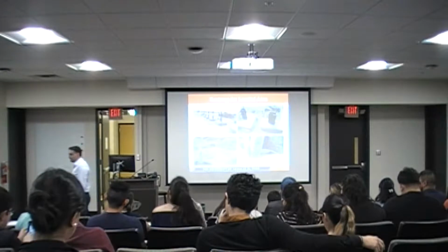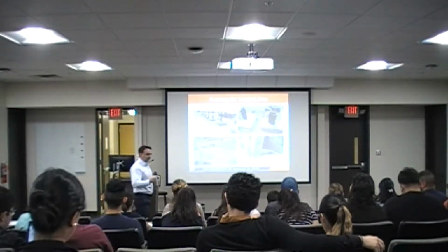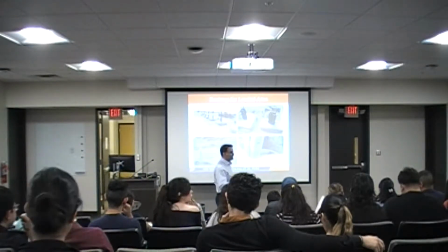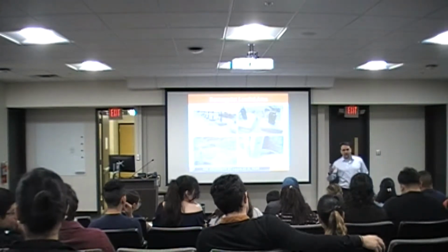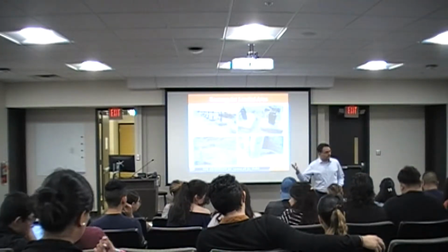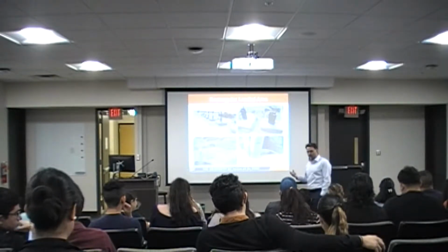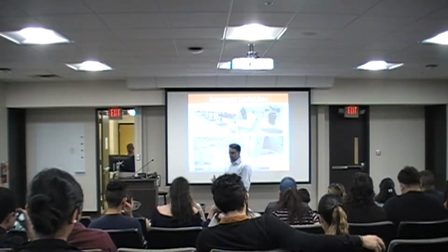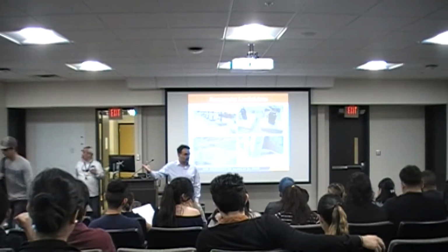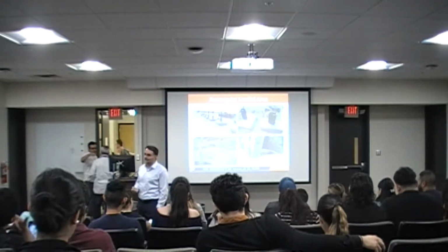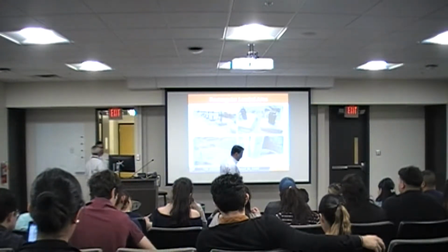How do you calculate factor of safety? Could you be over-designing, right? We're one step before that. We're talking about how do you calculate the factor of safety. Right, so you're basically looking at strength of the material, you calculate the stresses, and you compare the two, right? Basically the ratio of stress and the strength. You want to make sure that, for instance, for a factor of safety of 2, the magnitude of the stresses are half the strength of the material, because of the issues that we might face when we are looking at construction, bad inspection, and things of that sort that you might have.